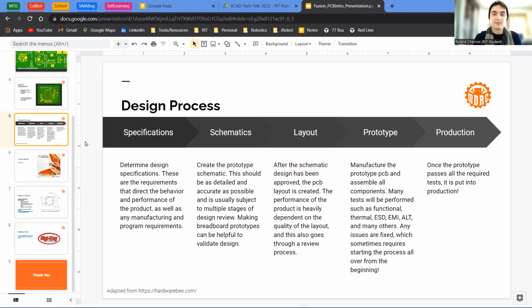There is a little bit of difference in PCB schematics versus a Fritzing schematic. In the PCB schematic, you have to always be thinking about, I am turning this into a physical thing. So every single part you place on the schematic represents directly a physical part on your PCB. That's really important to keep in mind when it comes to things like part numbers, sizes, where you're going to be ordering them, stuff like that, because you have to include all that information in the schematic. Otherwise, you're going to move to the layout and have no idea what's going on.